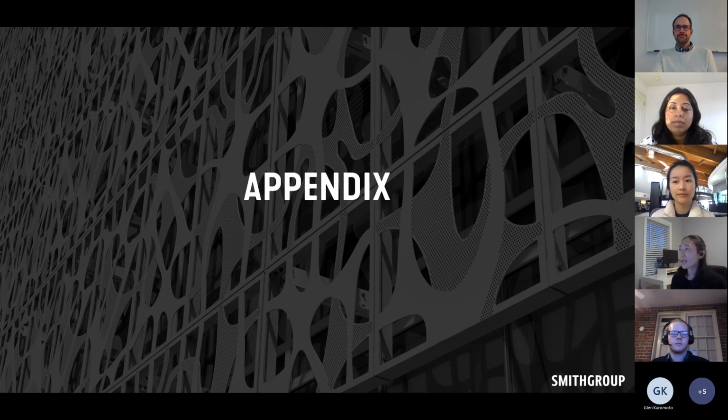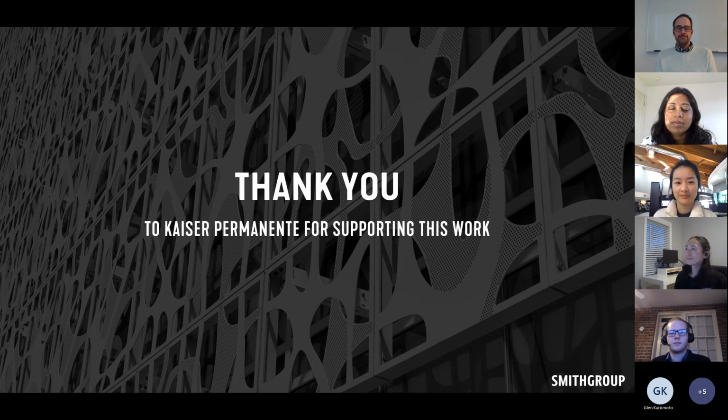Absolutely, thanks a bunch. This is great work. I know that it'll have a big impact in our basis of design. We normally see our engineers when they do load calculations for clinics, they do no diversity or 100% diversity, and then they add a 10% safety factor on top of that. And I think what I heard you guys saying pretty clear is that even with safety factors, you should be at 60 or 70%. And so I'm sure we just need to figure out how to roll this into our BODs.